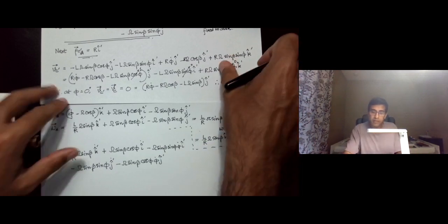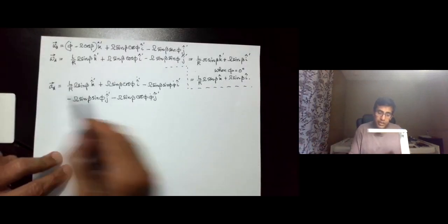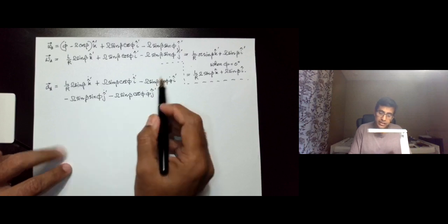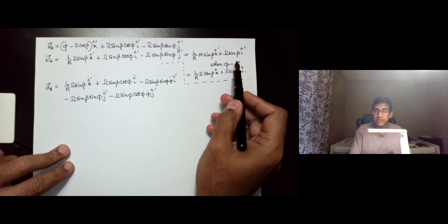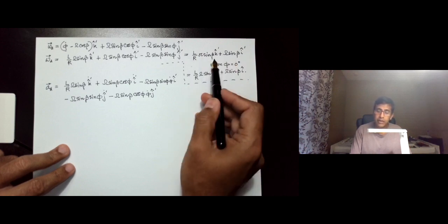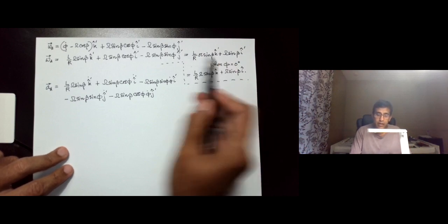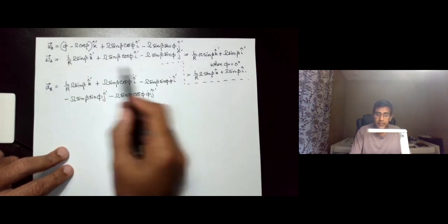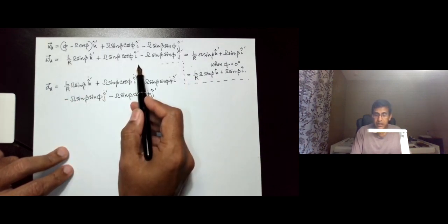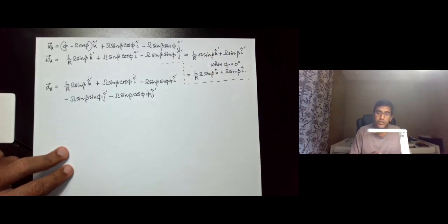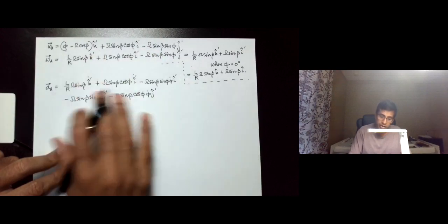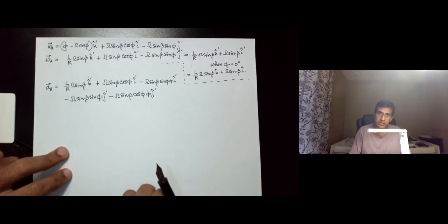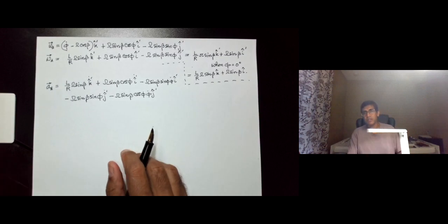We have to be very careful over here. When we find the acceleration, we should not work with this one, because this is a very specific velocity term. If we differentiated this, we would get an incorrect answer. We should take this general vector representation in our current choice of I prime, j prime, k prime. So we take the most general expression and differentiate it. Once the differentiation is done, at that point we can substitute phi equals 0.